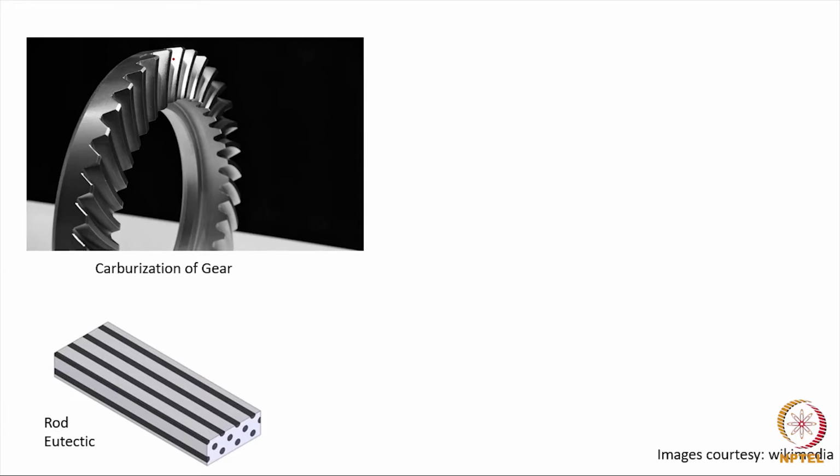So you can see that going from the gear, which is at the scale of centimeters or even more, to a eutectic, which is at the scale of a micron or 10 microns, we have a situation to choose the diffusion term either as planar or as cylindrical geometry given by the problem. So the scale of the diffusion process is very important.